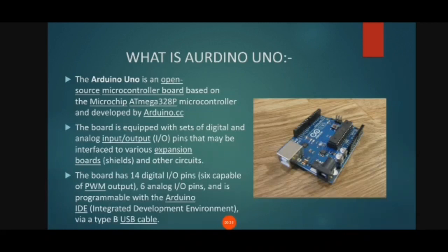The Arduino Software IDE includes a serial monitor which allows simple textual data to be sent to and from the board. The receiver and transmitter LEDs on the board will flash when data is being transmitted via the USB to serial chip and USB connection to the computer. The SoftwareSerial library allows serial communication on any of the Arduino Uno digital pins.